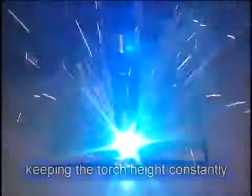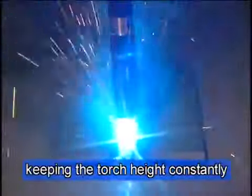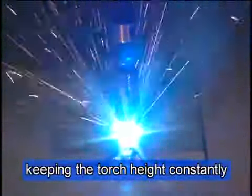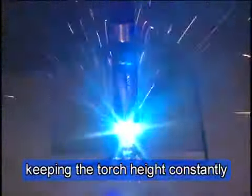One more important item to note when handling the welding torch is try to keep the torch tip height constant. In semi-automatic welding, moving the torch in and out should be avoided, although the above problem does not happen in automatic or robot welding processes.